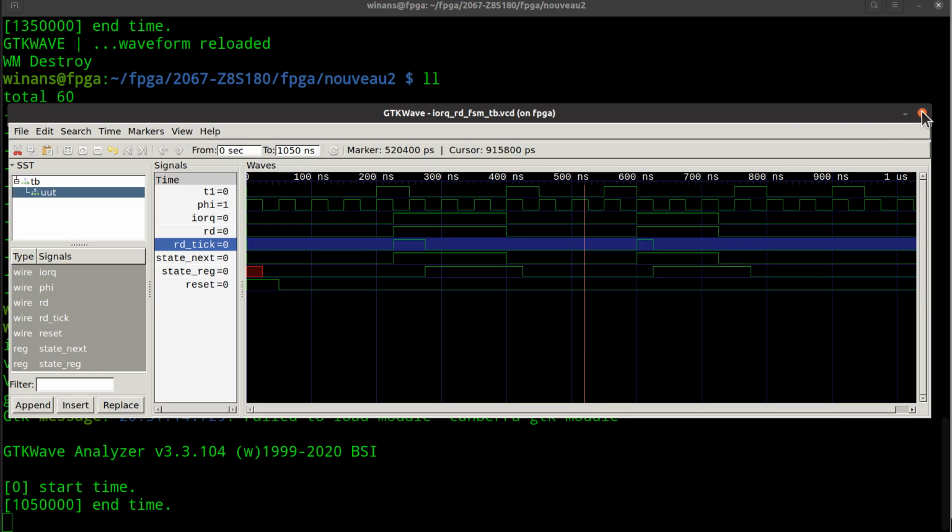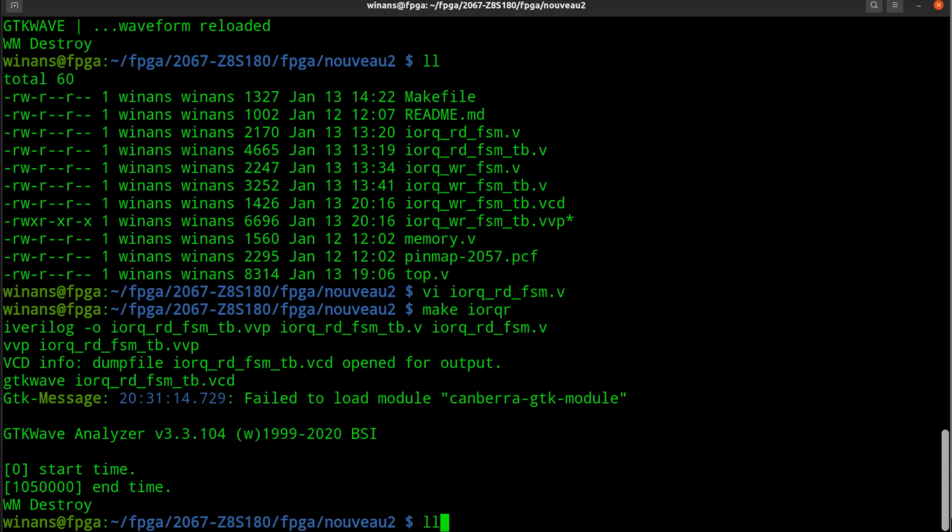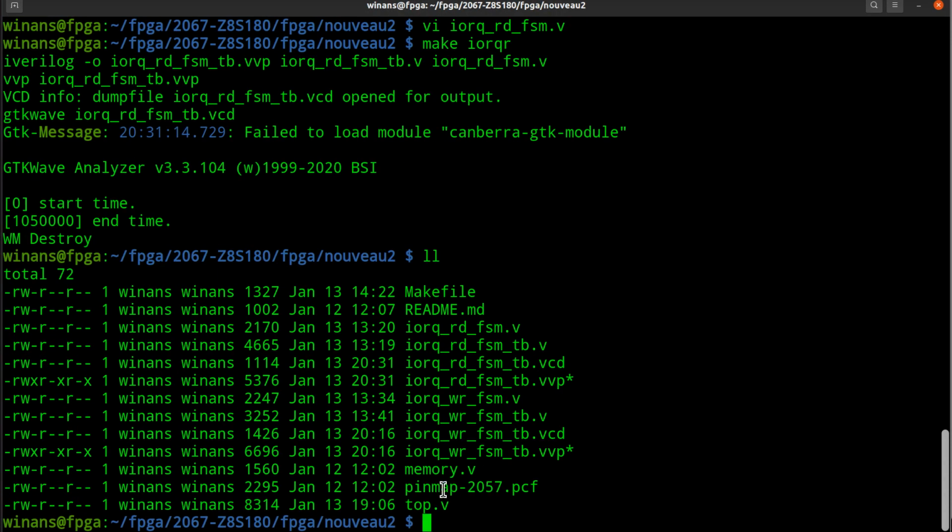Okay? This is not perfect, but it's what we want. If I did a fully synchronized thing using phi, then everything would happen so late. It would probably still work, certainly for the I/O case, because we have 3 whole cycles to do it in over here. But in a lot of cases, you don't have that luxury, and you need to get something to identify the situation earlier. So that's why I did this, and why I broke that design guideline. Okay. On the design of my read synchronizer recognizer thingy.